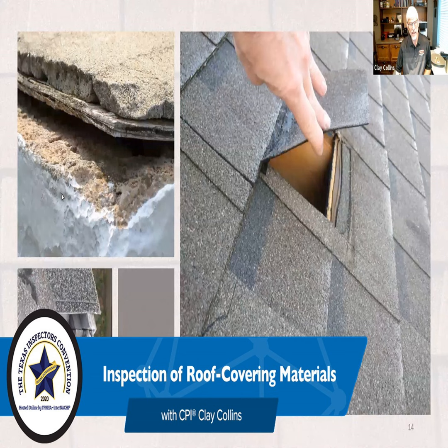But many times I see an almost flat roof down there at the eave to accommodate the multiple pitches. You've got to be very careful in those areas. But if you're up here in 4 and 12, you're pretty much good on anything.